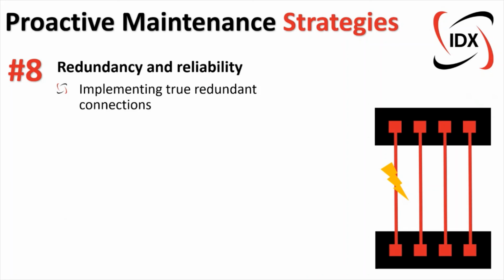An example of this is if you have a PLC, a critical component, and it's connected to an IO device in the field. You want to make sure that that IO device, no matter what, cannot fail for whatsoever reason. So you run 4 redundant cables between the single PLC and the single IO device using some sort of component, maybe a multi-channel repeater or a hub that often supports these redundant lines. But in this case, your cable probably isn't your weakest point in that installation, is it? Your weakest point is ultimately going to be your PLC and your IO device.